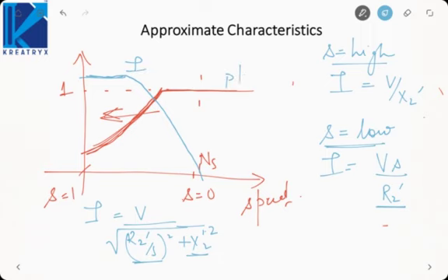This is your power factor. So at high values of slip, current is constant, and for low values of slip, as the slip reduces, current also reduces. Here, as the slip increases, power factor reduces. It is inversely proportional to slip. So this will be the plot of current versus speed and power factor versus speed. So as the speed of the induction motor is varied, the torque will vary, current will vary, as well as the power factor of the rotor will also vary.